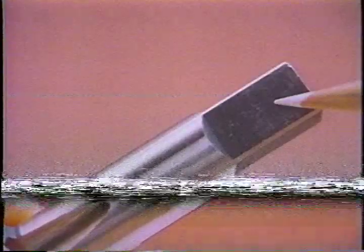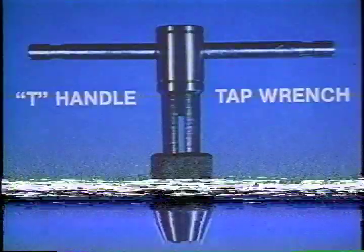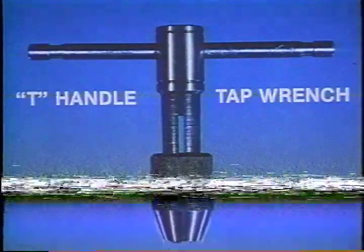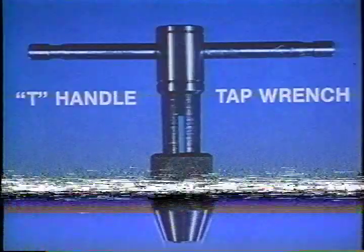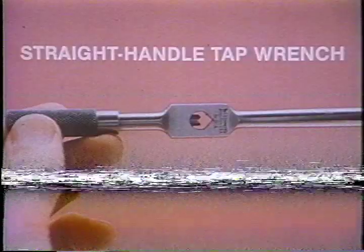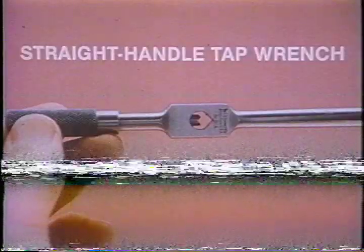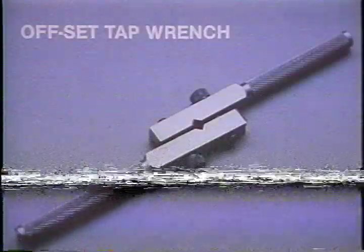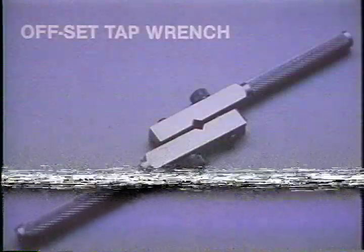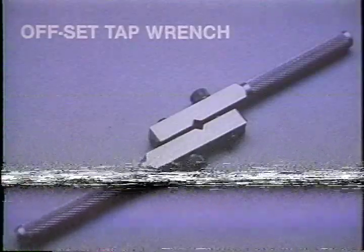The end of the shank is square, so it will fit some sort of wrench. There are several available. One is the T-handle tap wrench. It's adjustable and comes in a variety of sizes. Another widely used wrench is the straight handle tap wrench. This one is also adjustable, and so is the offset tap wrench. The longer handles of offset wrenches and straight handle tap wrenches have greater leverage and are more apt to break small taps.